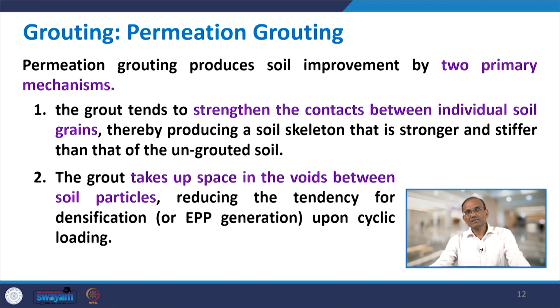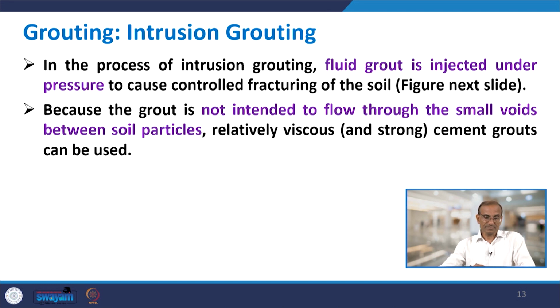The grout packs up space in the voids between the soil particles, reducing the tendency for densification, or let us say the generation of excess pore water pressure will be reduced upon cyclic loading. So, first of all it will strengthen the contact between individual soil particles, and it will also fill the voids. As a result, the generation of excess pore pressure will be reduced, that means chances of liquefaction will reduce.